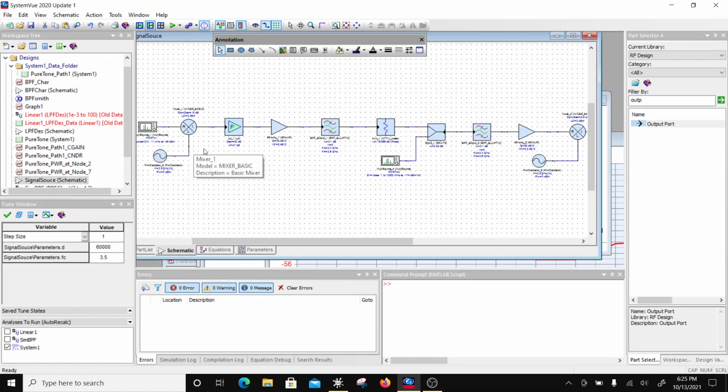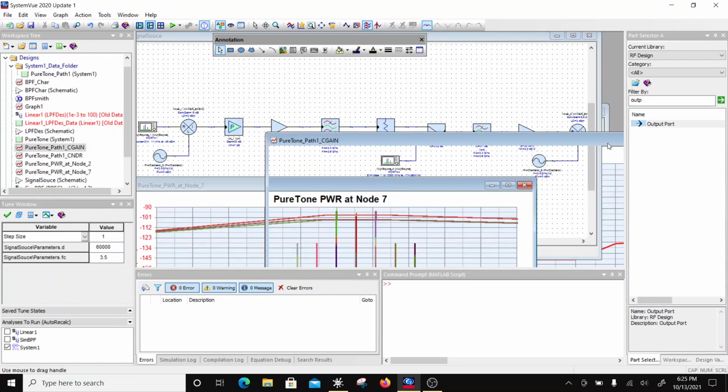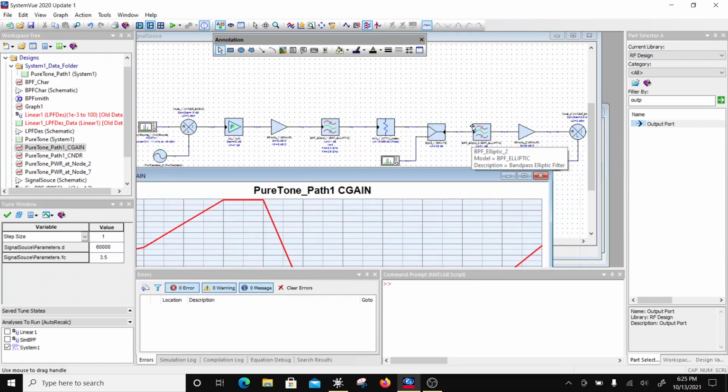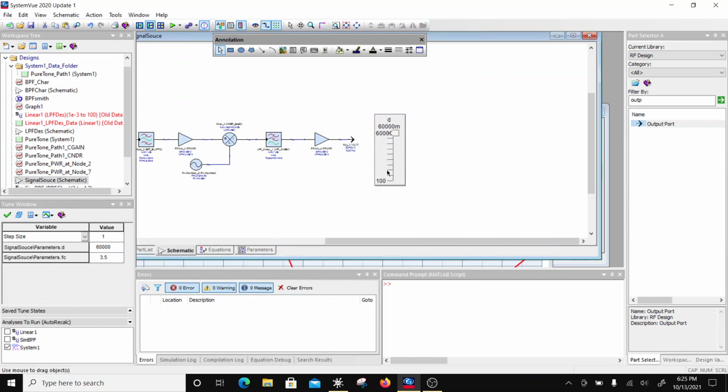So in this chain you can vary a lot of things. You can look at signal to noise ratio at any point, and you can look at the compression characteristics of various stages using cascaded gain across the channel. You can also see whether you are in the right range of the detector. If there is an ADC, you have to be in the range of that ADC, and you can put a variable gain in here to meet the right range of the ADC, or rather the right distances to which the receiver is going to respond.